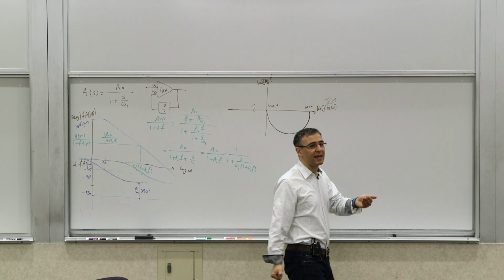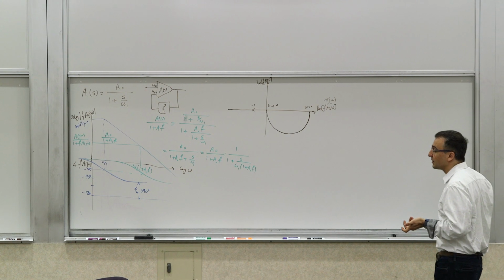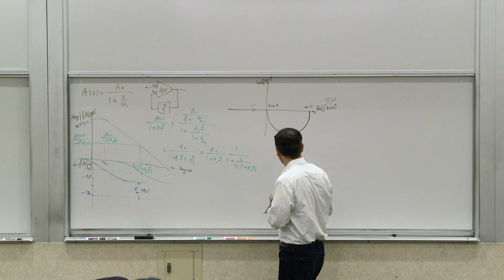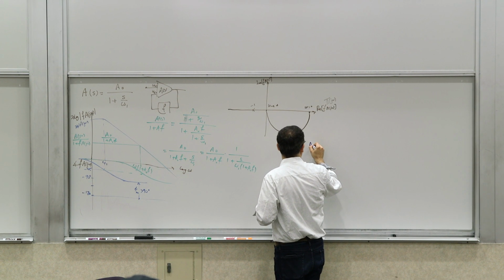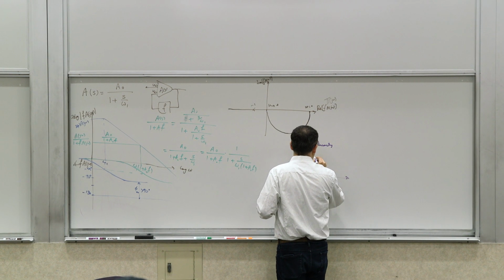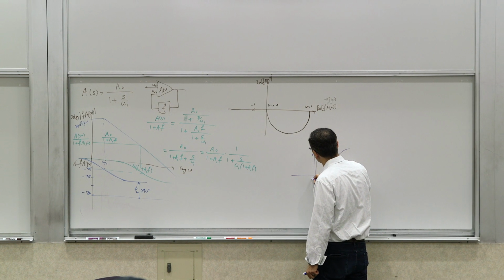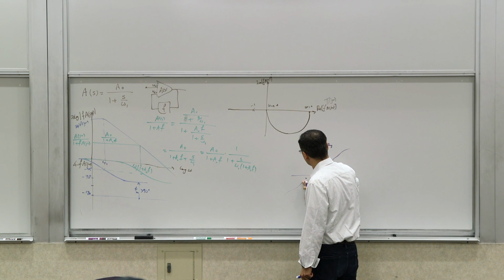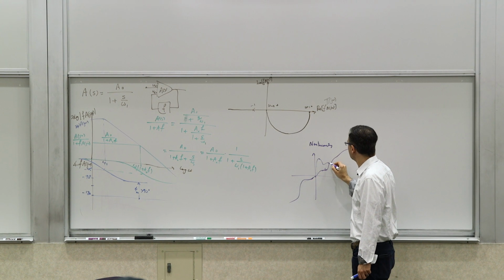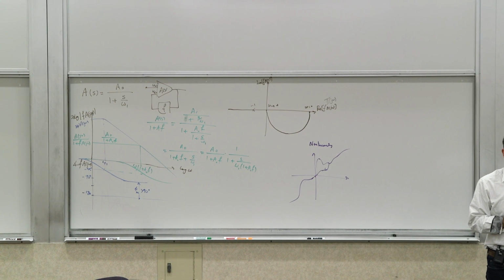Now how about if you had nonlinearity? Now we can apply the circle criterion, right? So let's say you have a nonlinearity that's confined to the first and third quadrant. Some shape with even hysteresis and time variance and all those things, but it's remaining in the first and third quadrant.